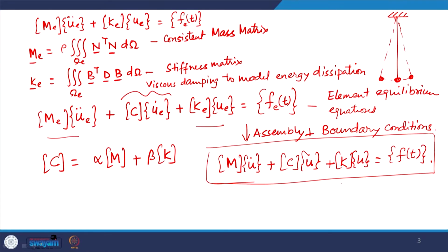If the dynamic terms were not there, then it would be simply a quasi static problem. But if the frequency of excitation is reasonably close to the natural frequency of the structure, or very high compared to it, then the dynamic effects are important and the complete system needs to be modeled.